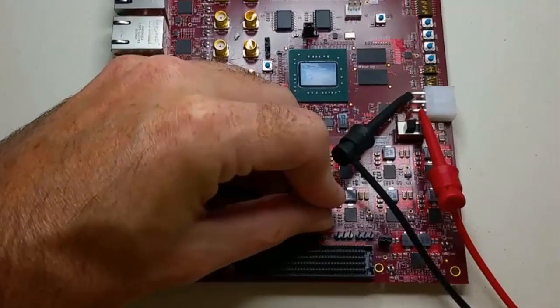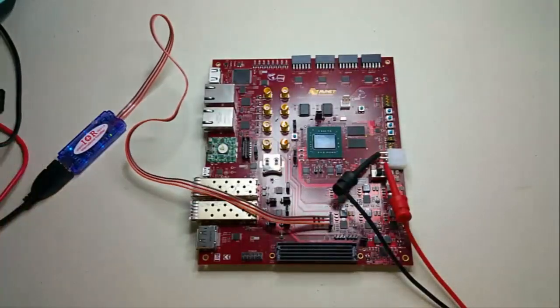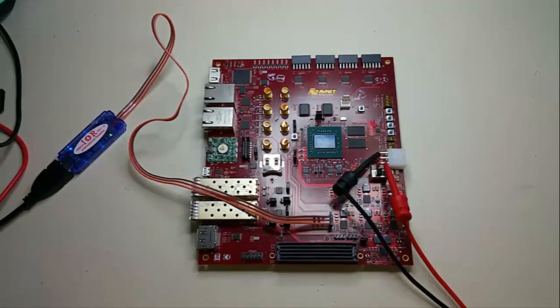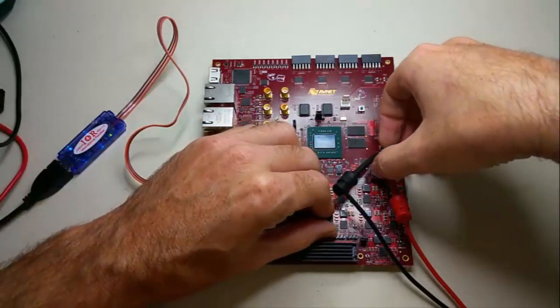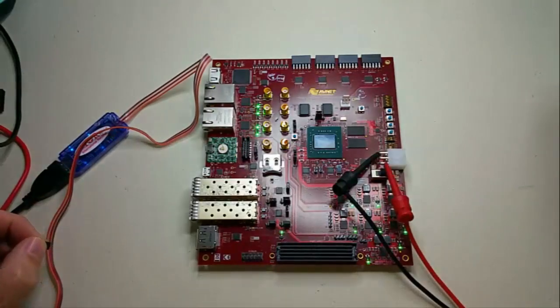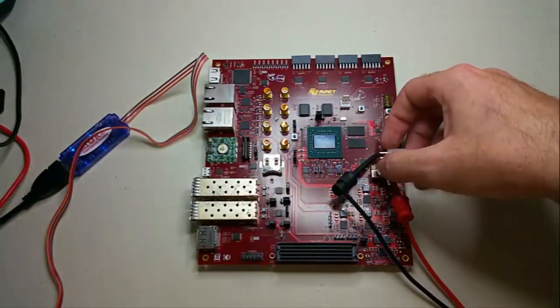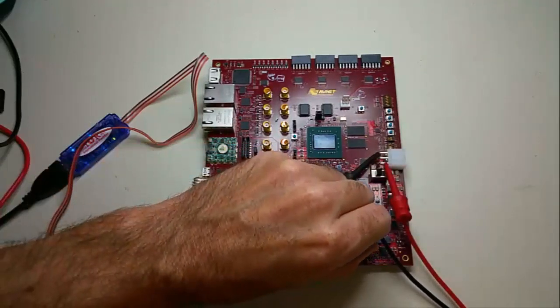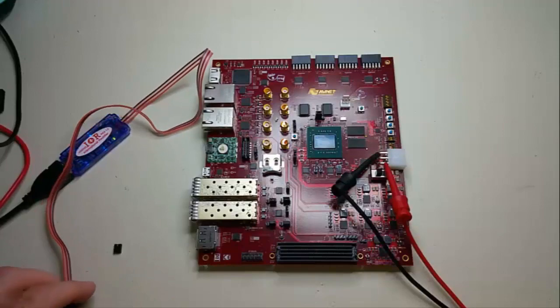Then we take our I2C to USB hardware dongle, plug that in, and then we plug this dongle into our computer. So now we'll be able to communicate with all the devices while their outputs remain off. This will also let us program the devices so that the next time we power up the board, you can see that they're all programmed. Now in this particular board, I've already programmed all the outputs, so what you would do after you program it is you would power down the board, which is already powered down, and the next time you power up the board with the jumper removed, you'll see all the supplies come up as they should. Just to show you, if you keep that jumper on, all the outputs are still disabled. So since this board has already been programmed, what we'll do now is actually look at the GUI itself so you can look at the information that's returned to the screen while monitoring this board while it's powered up.